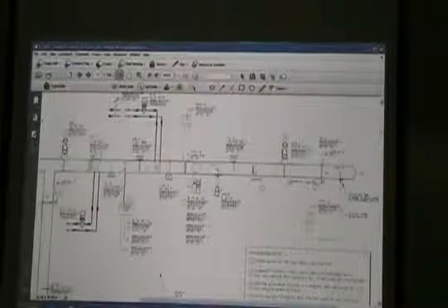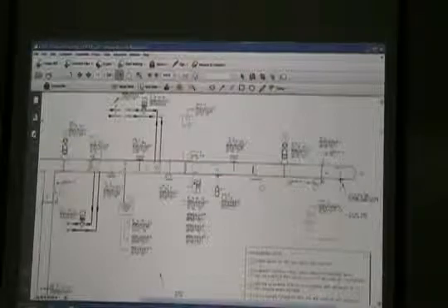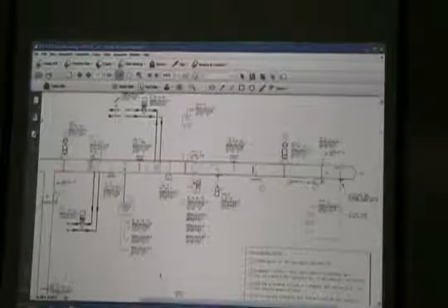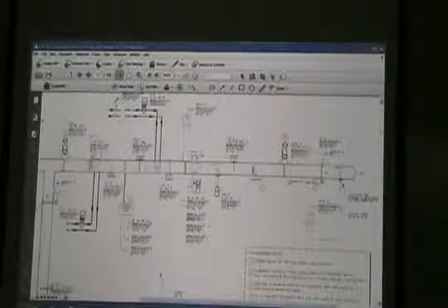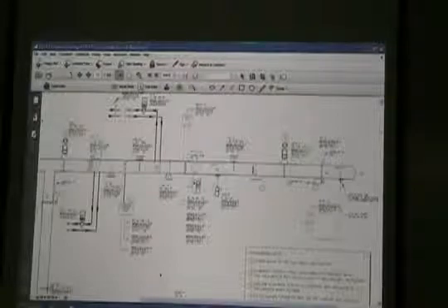So if the patient room is at 6 air changes all the time, nothing's really varying. And if it's designed as a constant volume box, which might be more than 6 air changes, but 6 air changes might be the max and the minimum. So we have all our boxes out there at a constant volume position. They're not really responding to a mostly closed position. They're never going to go closed.